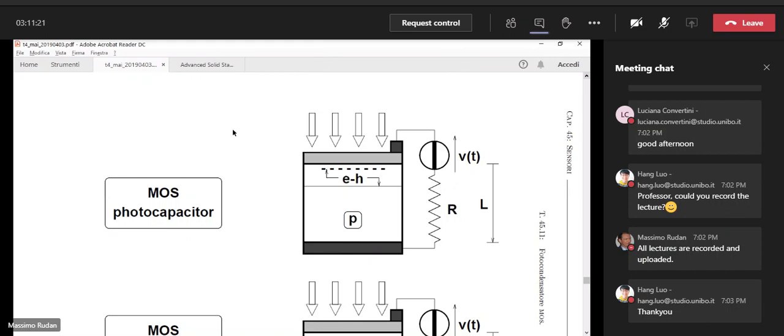But we don't have yet the inverted layer because the inverted layer takes time to form. The formation of the inverted layer is not immediate, okay? What is almost immediate is the formation of the depleted region, okay? So from the dynamic point of view, when we apply the large positive voltage, we have the instantaneous formation of the depleted region in the semiconductor with no inverted layer, okay?